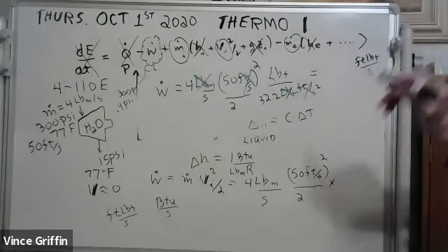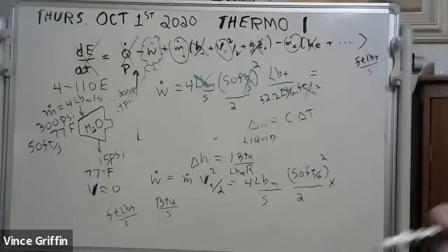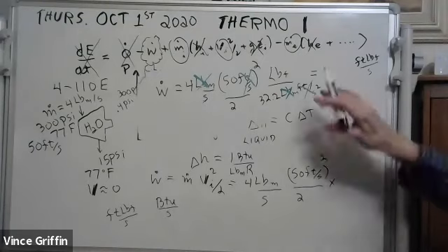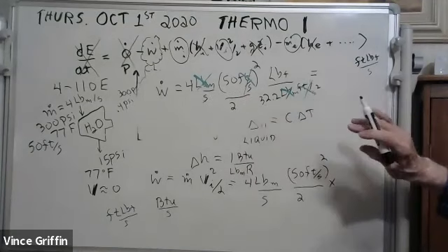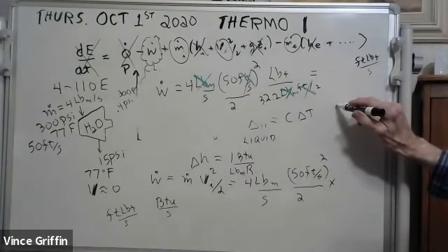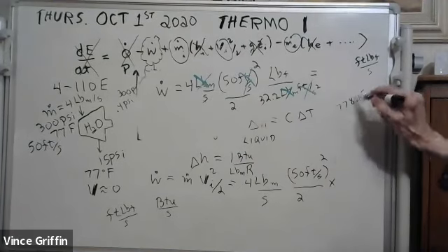This will give you foot-pounds force per second. And I tell you what it is. Oh, gee. Oh, my time is up. Oh, it's so sad. But you could just multiply these numbers and you could get that. And if you wanted BTUs, you have to divide by 778.15.